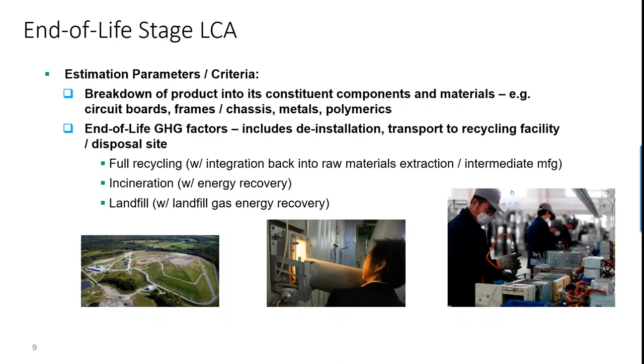And then end of life, the last stage in a life cycle assessment, we wanted to make sure we captured all the constituent materials and then looking at what is the end of life scenario for that. Is it full recycling? Are there materials that are incinerated with energy recovery just to get at the metals? And are some materials inadvertently getting into the landfills? So that mode had to be taken into account when we did our life cycle assessment as well.